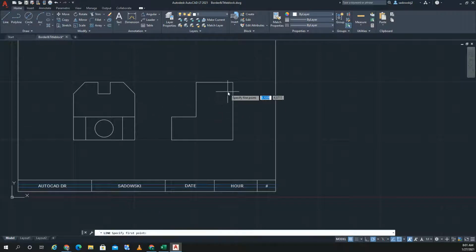And bring this line over. Remember, I stopped that segment there. I made a little segment there so I didn't have to do any trimming later on. We've got a hidden line in here that's offset. It looks like it's offset 0.5. And then we've got the lines for the holes running through here. So let's do those. Top quadrant of that one.